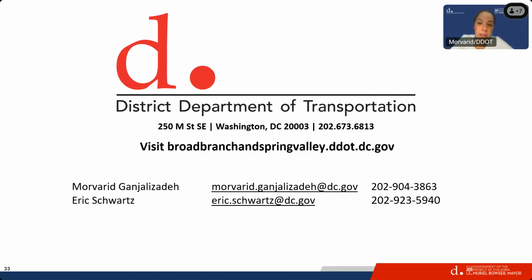I should have mentioned in the design, when we design the facilities, they're designed to the point that there's no ponding. Most water drains within the 72 hours. So I don't think, if there's no ponding, we'll actually have any mosquitoes. They will not attract any mosquito because they drain within the 72 hours of the storm. So that's what I think.